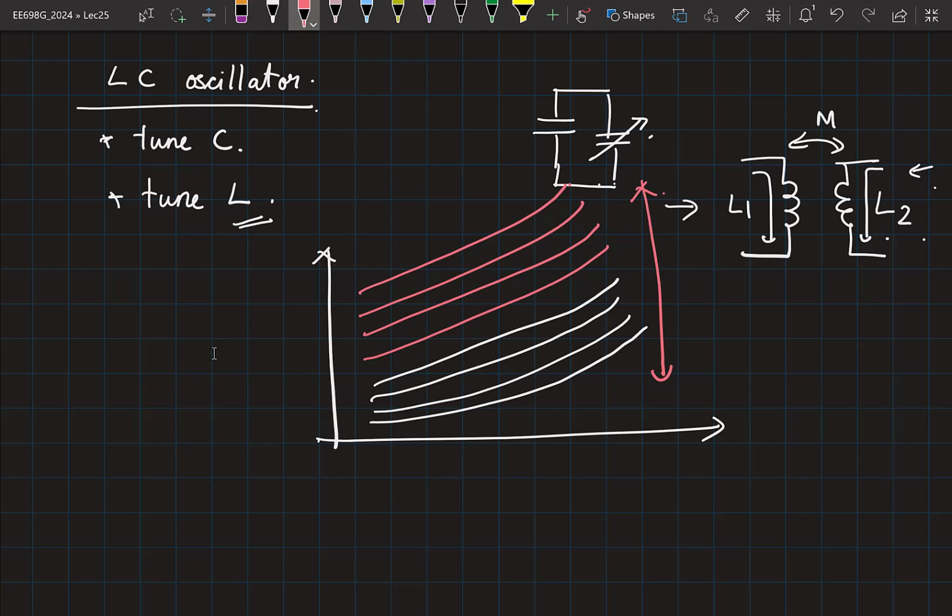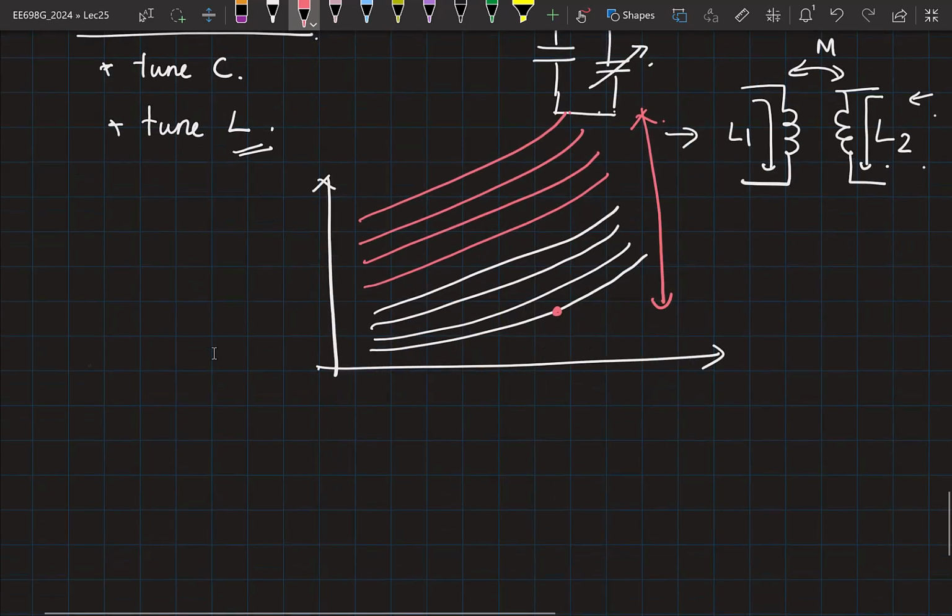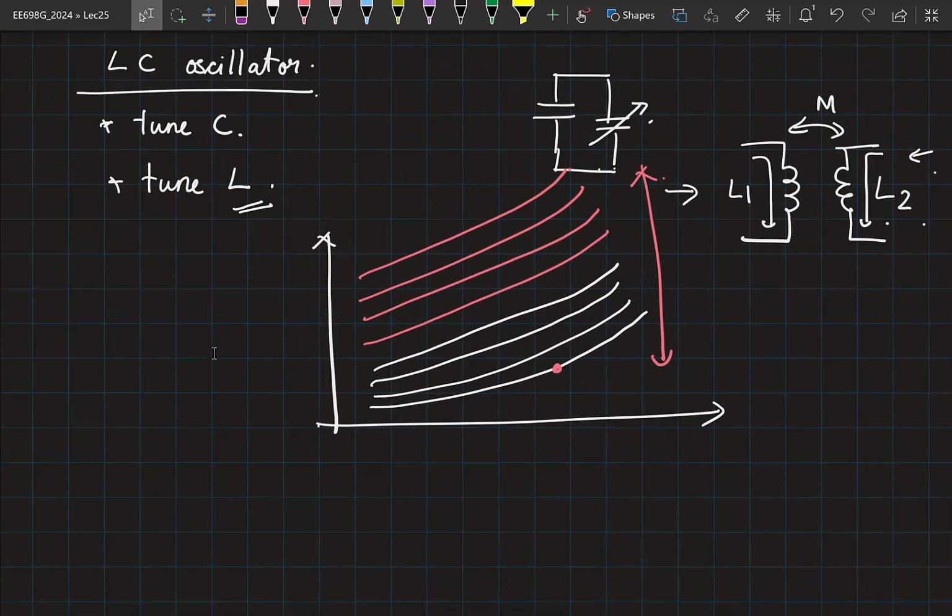Typically, because we have not seen how the oscillator is in feedback, we will discuss this after we have seen how to put an oscillator in feedback. But that usually requires two types of algorithms. One to identify which curve and then how to move along that curve. So two separate algorithms. Finding the curve also takes some effort. But the good part about it is that finding this curve requires digital tuning, because you don't even need an ADC.